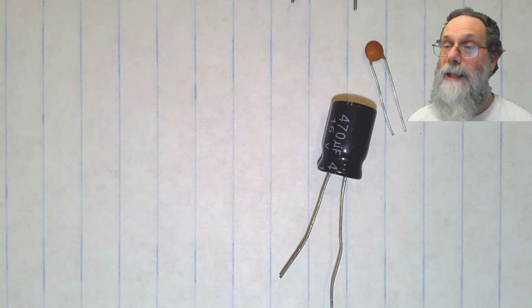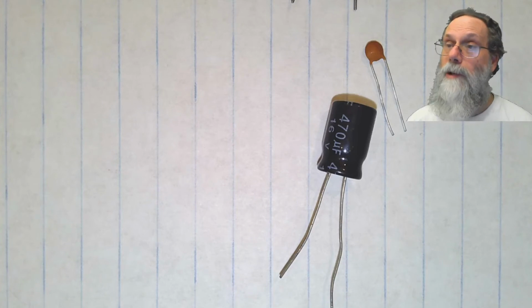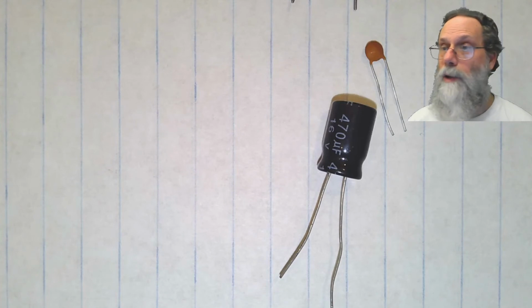The aluminum plate, in fact, is roughened so that it has a very large surface area. The aluminum oxide makes a very thin layer over that large surface area. So you have a very thin layer of a very large area, which allows you to get a large capacitance, even though the material itself is not that high a dielectric constant. The aluminum oxide is not much higher than plastics. So it's not like the ceramic where you got the capacitance by having a very high dielectric constant. Here you go for a very, very thin layer.